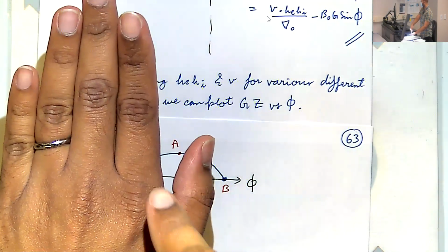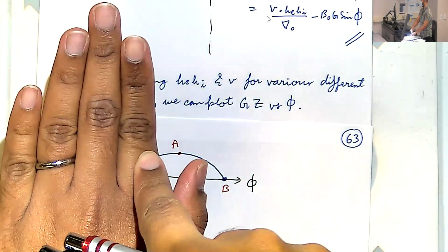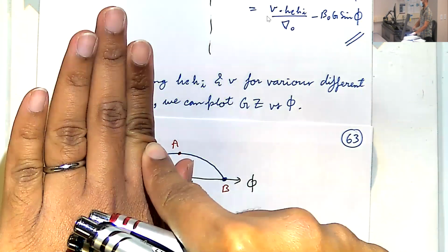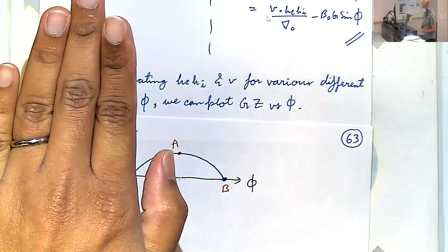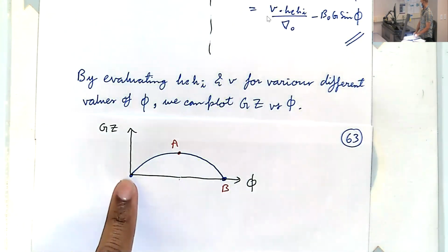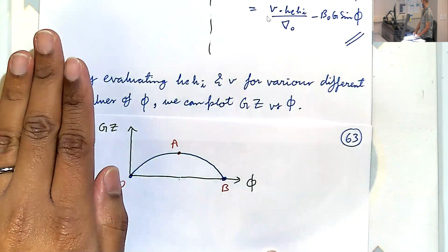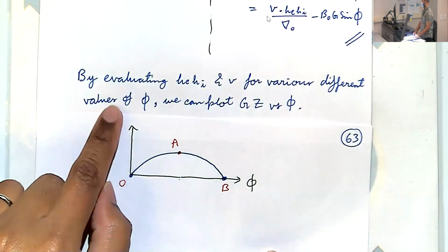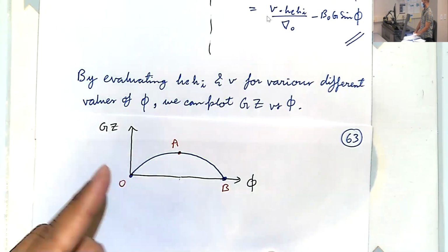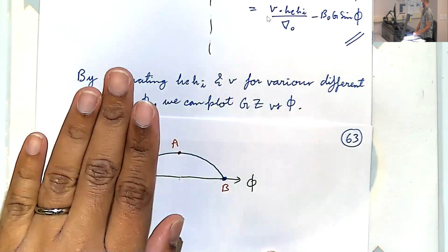And if you push down one side, then you expect, okay, then I hope I get some restoring torque to come back to this stable position. So that's what this graph is showing us. At phi heel angle 0, we have 0 restoring arm. Okay, 0 restoring moment arm means 0 torque or 0 moment.